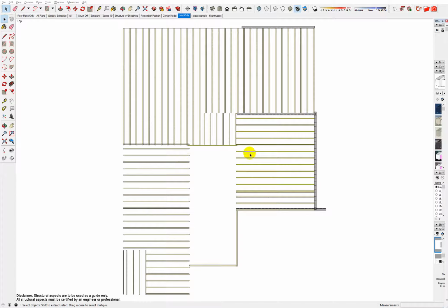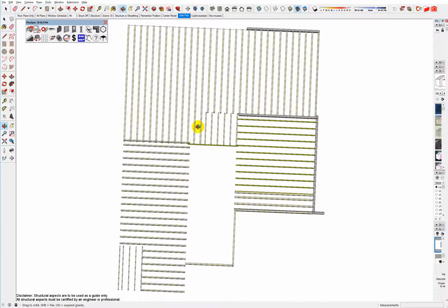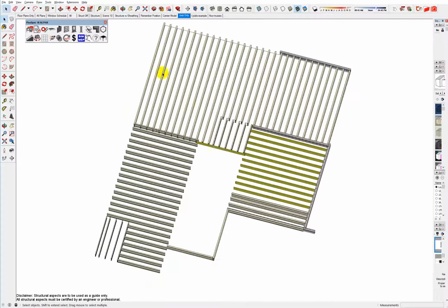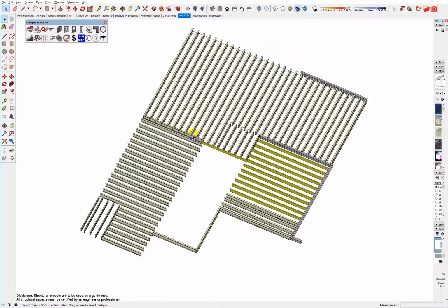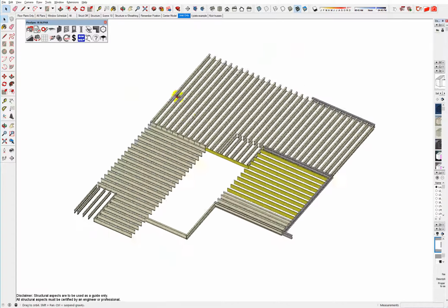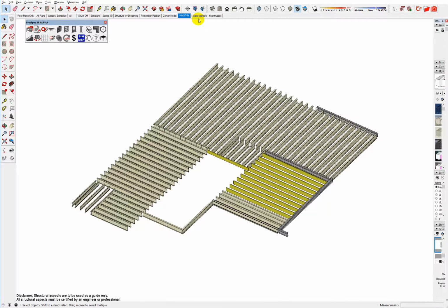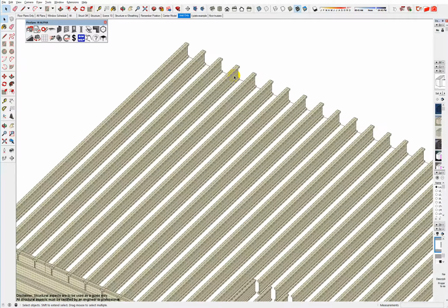Now, typically a joist manufacturer or a timber supplier would go through and do a joist layout. And it's kind of difficult to get it right. And it's the difference between winning a job and losing a job in many cases, understanding how much waste you're going to have. And a job like this, it could be several different types of joists to figure out the most economical way of doing it. And in this case, I'm using I-joists here.